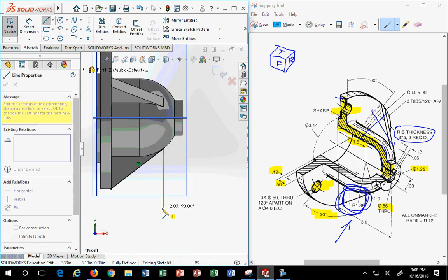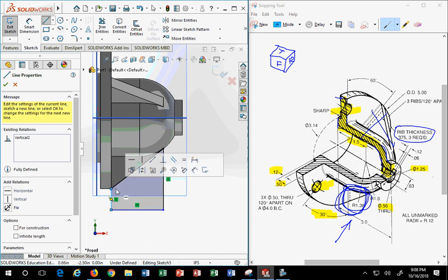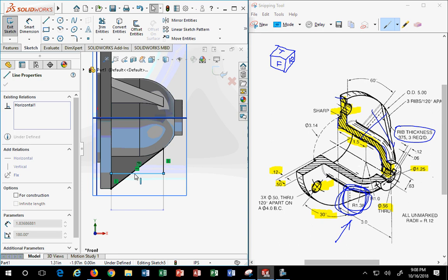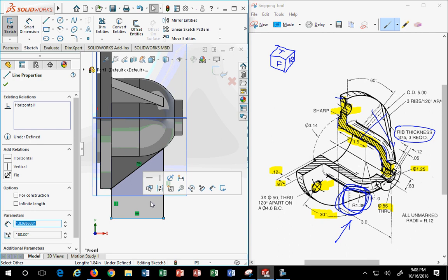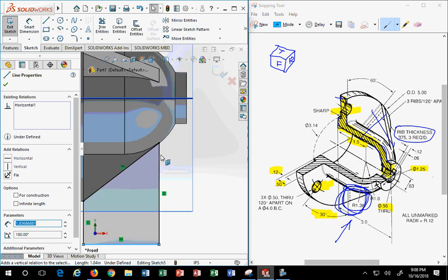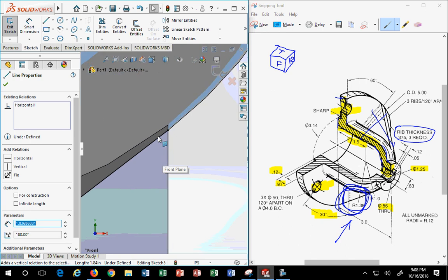Now, if I just literally make an extended feature out here, who cares how far out. What does matter is you can't have it in, for obvious reasons. And you can't have it angled in any way, because that means your cutting tool is going to cut into this part the wrong way. It has to cut in straight, head on, like it would on a real lathe. That's the interesting part. For those of you that have done real lathe work, you know what I'm saying. The tool has to go in exactly in that position, otherwise the cut will dig into the part. So in this case, everything's aligned beautifully. You can't make a more pretty cut in the real world.